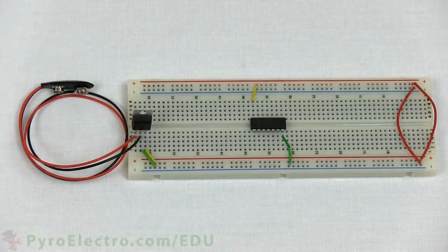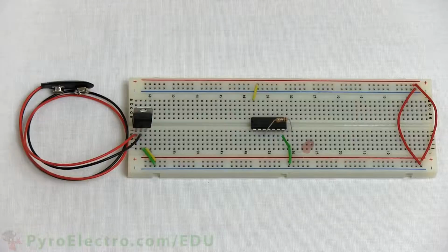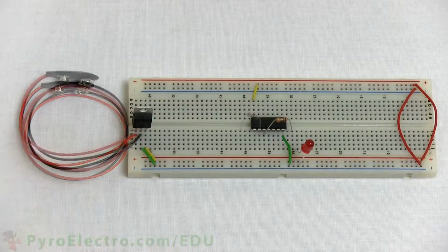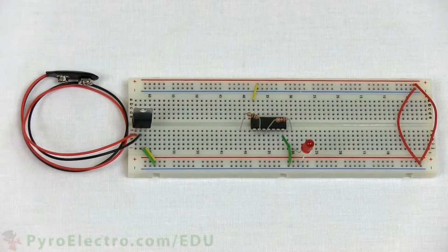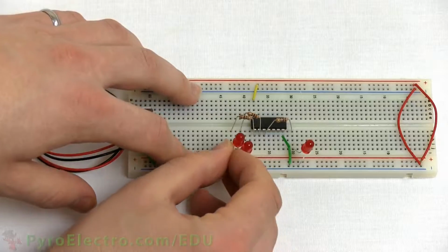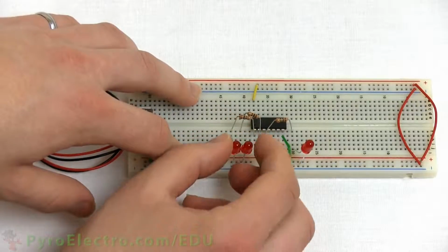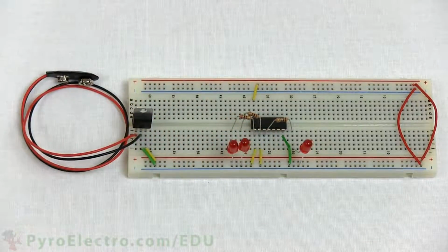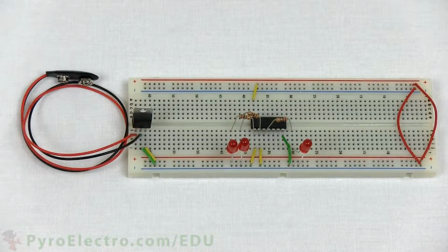And now we're ready to test the AND gate. To confirm the truth table, we'll need to give the AND gate 2 input signals and view the output. As per the schematic, we'll connect 3 100-ohm resistors to the AND gate at pins 1, 2, and 3, and then connect each of those resistors to an LED that goes to ground. These 3 LEDs will represent the 2 inputs to the AND gate and the 1 output from the AND gate.